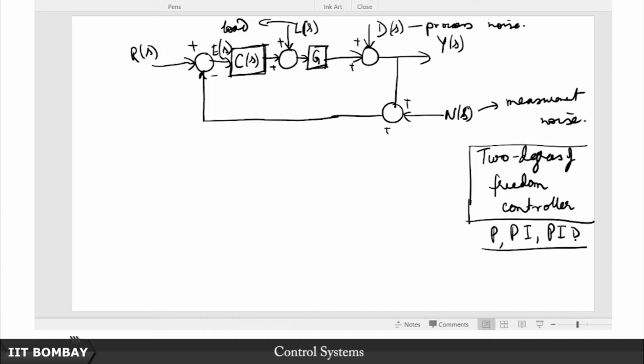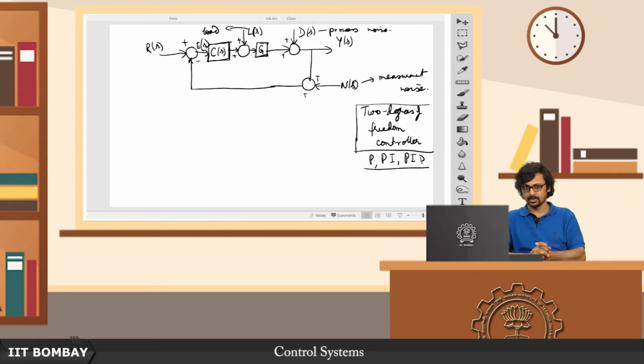Okay. Again, to reiterate, all of this requirement and all of these demands are valid only if the system is stable in the closed loop. If not, none of this makes any sense. So do remember that. Once you have learned sophisticated techniques of checking the stability of a system, you should never jump into the solution of a problem without first checking whether the system is at all closed loop stable. Yeah, you might be in for a rude shock. You might have designed all the things nicely and you might feel it should work, but then suddenly you simulate the system and things blow up. The reason being that you haven't checked for the closed loop stability.